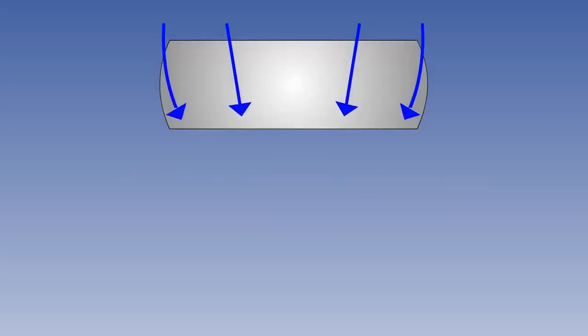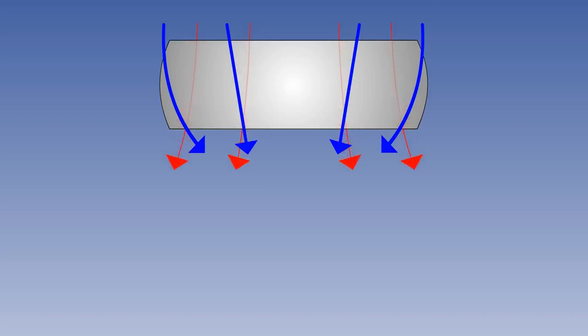The airflow over the top surface of a wing is at a lower pressure than that below the wing. The two flows are modified by this pressure differential, which creates a spanwise element towards the root on the top surface and towards the tips on the lower surfaces, and these flows interact at the trailing edge and wingtips.